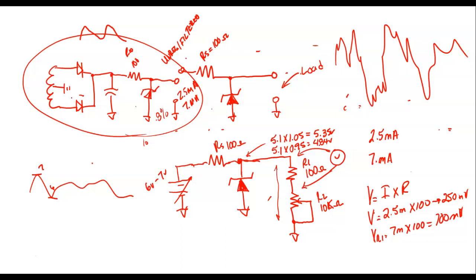You understand that? So what we did is we put a static input on it so I could set 7 volts and do all my measurements, set 6 volts and do all my measurements, set 2.5 milliamps, set what? 7 milliamps. And once I prove my Zener circuit, then now I know it's designed. Now the design of a power supply always starts right here at the load. What load do you want your power supply to run? That starts the design of the whole thing.